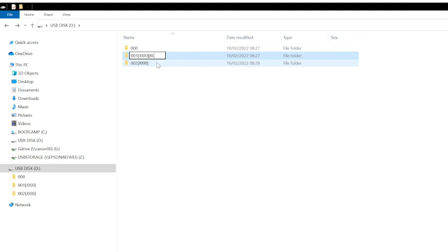So in our instance we want to close relay number 1 whilst the folder is playing, so we put 1 in there and we put 0 next to it, and we just close the brackets again. So basically now when that contact input is triggered, the relay 1 will close, and obviously when the folder is finished playing it'll jump back to 0.